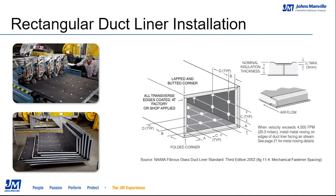So the type of transverse duct connection that's being made, where those two sections of duct come together, really dictates the width of the liner that you're going to need, whether it's a slip and drive connection or a TDC connection. The type of sheet metal connection dictates the type of insulation width that you're going to be using.